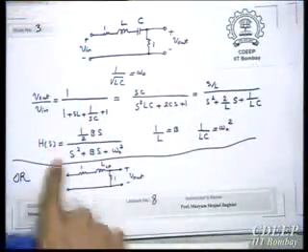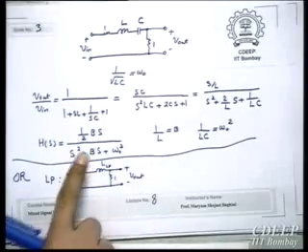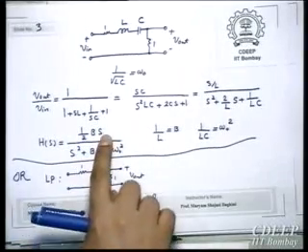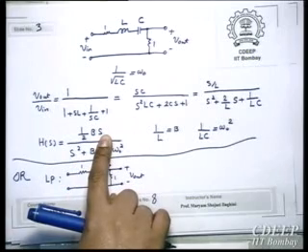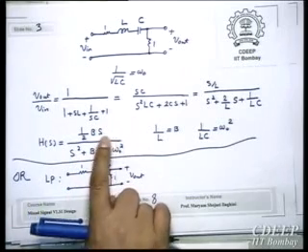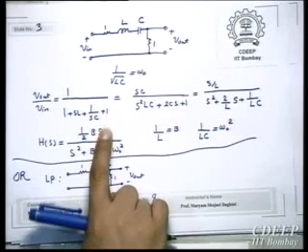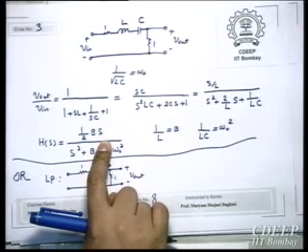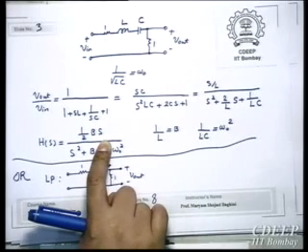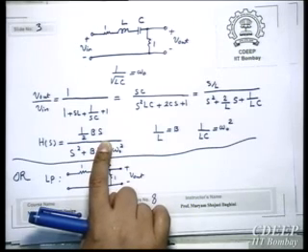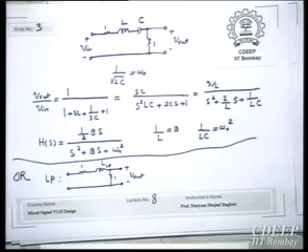Okay, so now see, effectively this biquads, this second order, you learn this relation. This is a very useful relation for band pass, low pass and high pass. Because just S changes. If you remember, for second order low pass, this was just a constant. For band pass, it will be S, and for high pass, it will be S square. Now, there are general purpose second order modules which are available. Standard. You don't need to memorize them in design references.